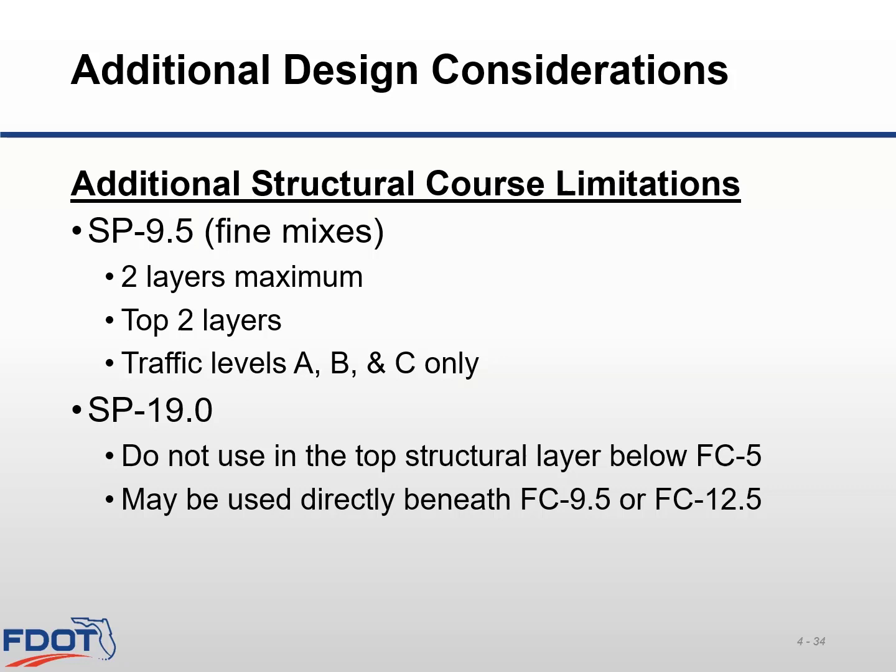So the decision was made at that time to limit the use of 19 millimeter mix directly beneath an open graded friction course, and we simply stuck to that decision. Again, our mixes are substantially better these days, and it may not necessarily be as much of an issue now, but our preference is to continue the practice of only placing SP 19.0 under dense graded friction courses.